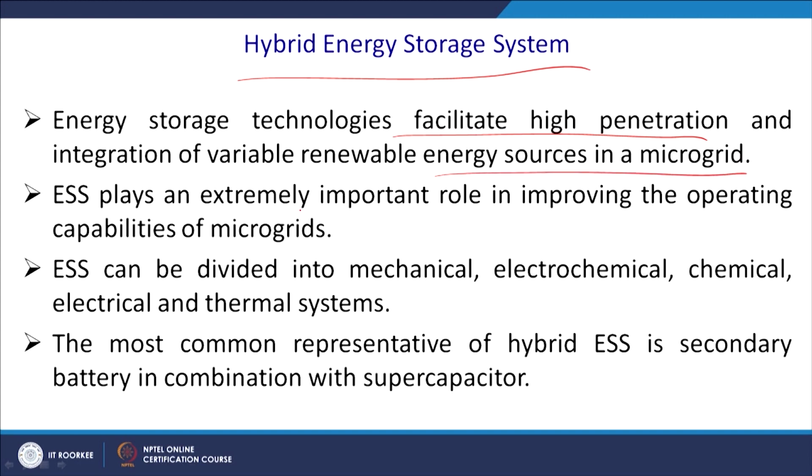ESS play an extremely important role in improving the operating capabilities of microgrids. ESS can be divided into mechanical, electrochemical, chemical, electrical and thermal systems. So, you can have different ways, but generally it is electrochemical, mainly batteries, but you may have a fuel cell, hydrogen, all those things we have seen in our previous lectures.